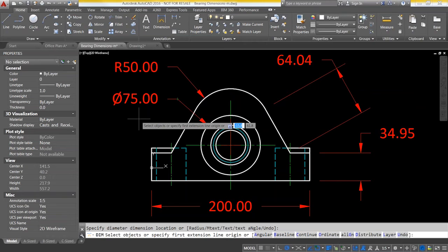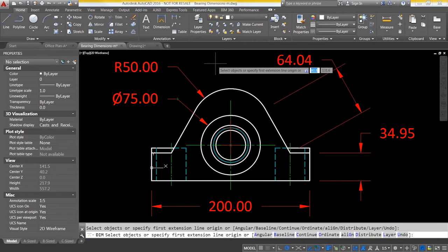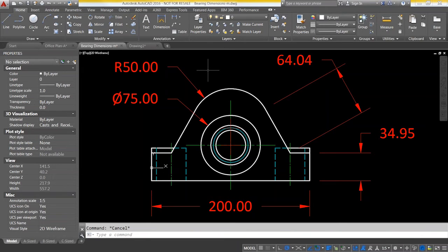I don't know whether you've noticed, but I've been putting all of these different dimensions in with just the one command sequence. Just the one. I haven't been swapping from measuring a radius to a diameter, doing an aligned or a linear. It's all capable with the one command, which is really, really quite nice. Now, something else you may or may not have noticed here is the color of my text. Okay, it's red, big deal.